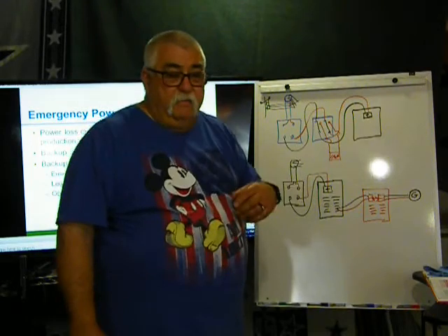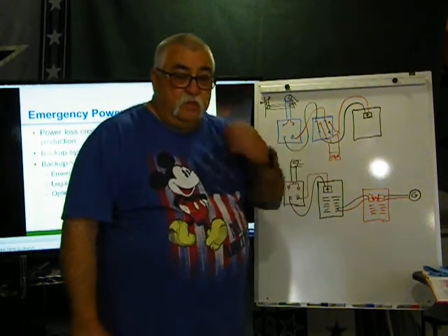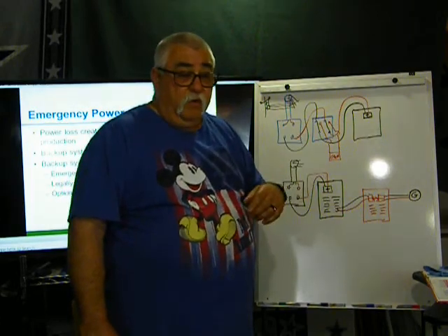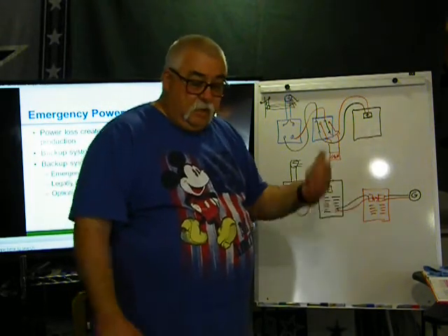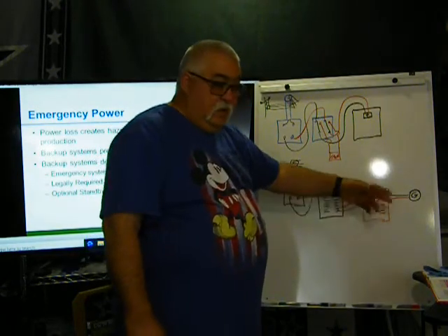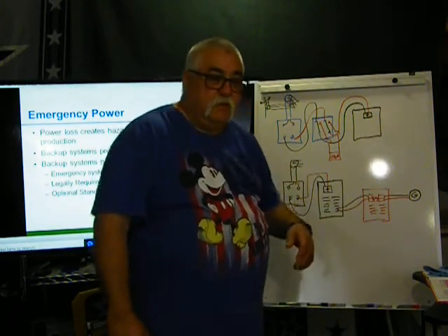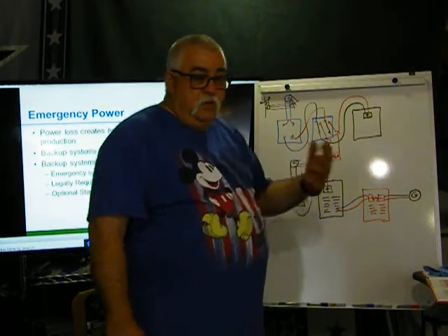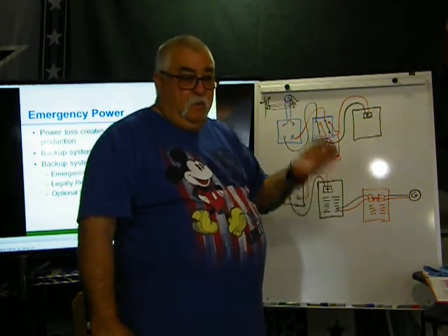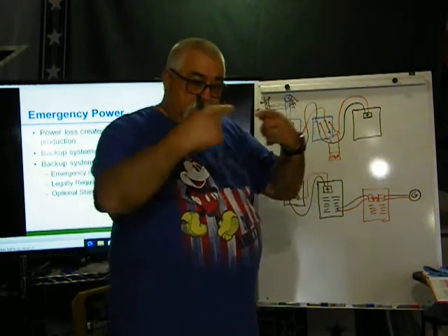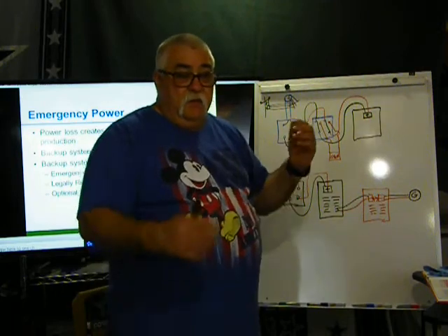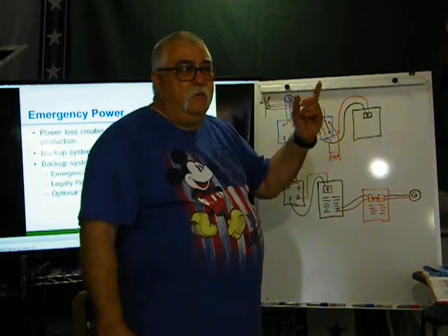The one that I heard about was somebody who worked for the utility company, and they hooked it up 240 volts. They had a big generator, and they had a manual transfer, and had 5 circuits moved across. Well, what happened was the generator is like a 9,000, 10,000 watt generator, and when the power came back on, you had two sources coming into the same panel. It blew the transformer up.